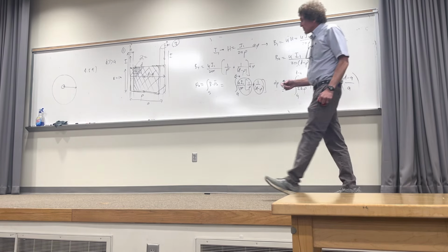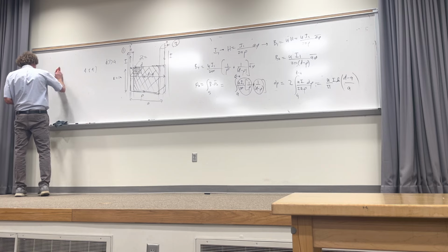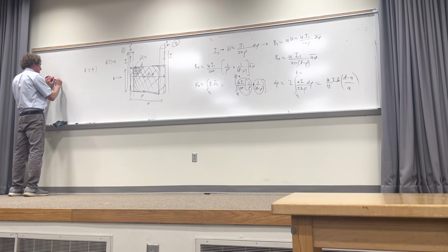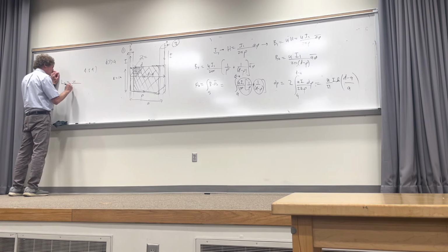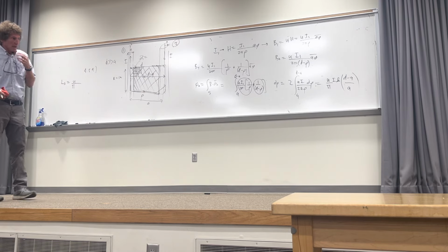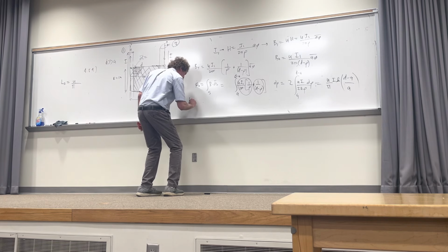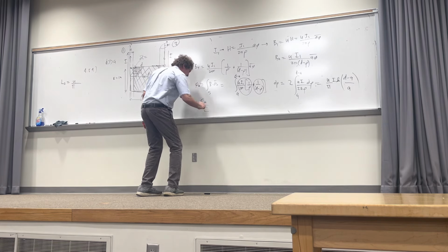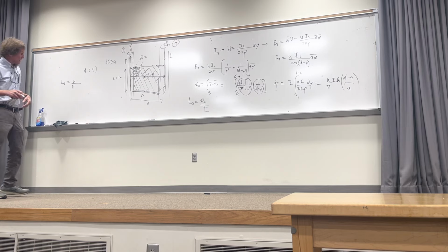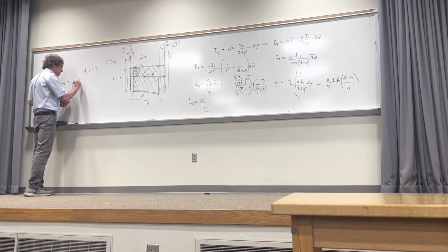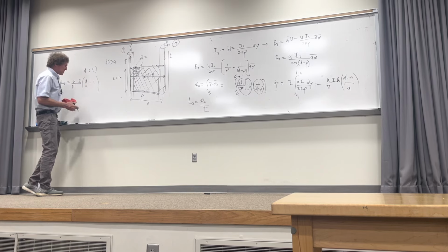So that means, therefore, that the inductance per meter of this one, ignoring the internal fields there, really the self-inductance per meter would be equal to mu over pi, because I should put it here. Inductance is going to be equal to the magnetic flux divided by the current causing it. The current was I. Inductance is never going to be a function of current. Do y'all agree with this? And then over here it's going to be mu I times the natural log of d minus a, or it could be d over a minus 1. But that's going to be the same.